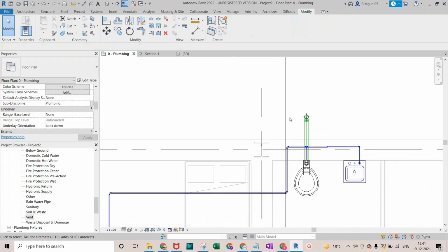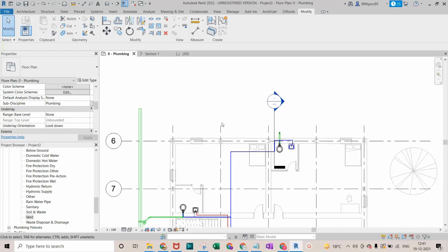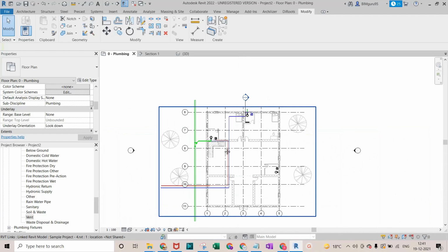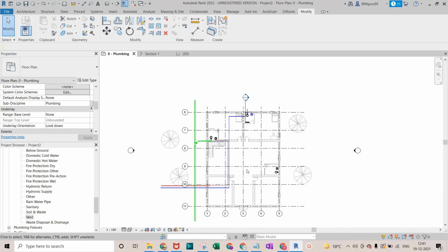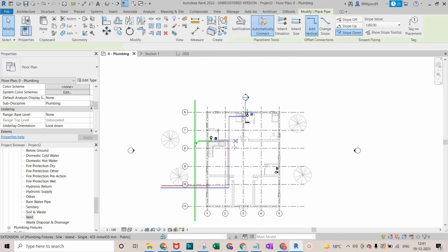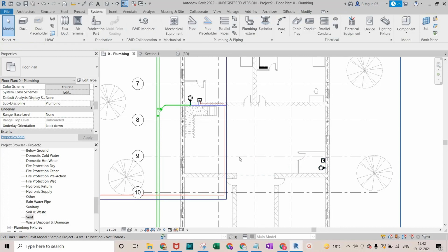So vent we already covered, water supply done, drainage is done. Now if we go with the chill water connections. Chill water, we are now considering for drainage part or water supply part. It will be considered in HVAC mechanical part, but because this is the piping system, we'll cover these pipes in this one as well. So chill water connections will be for the FCU only, so FCU and AHU specifically, the units I'm talking about.